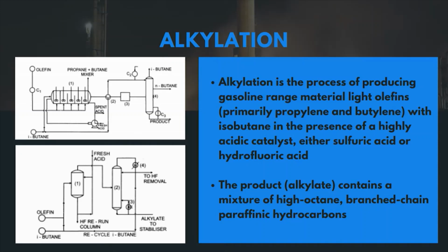This is known as refinery configuration, and of course, if you want to produce lubricants, then accordingly you have to procure the corresponding crude oil. With many units in a refinery, the refinery complexity will go up. Apart from the cracking units, we have some more process units which we are going to cover right now.